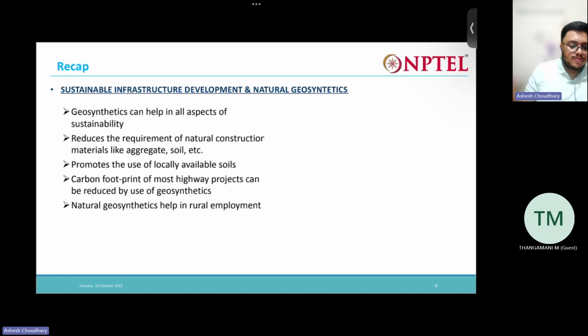So to prevent that, there are many things that are used. One is we can use many types of breakwaters, or groins. We can use these zigzag groins as a barrier in the water. So whatever erosion is occurring through this lateral drift of the waves gets prevented.